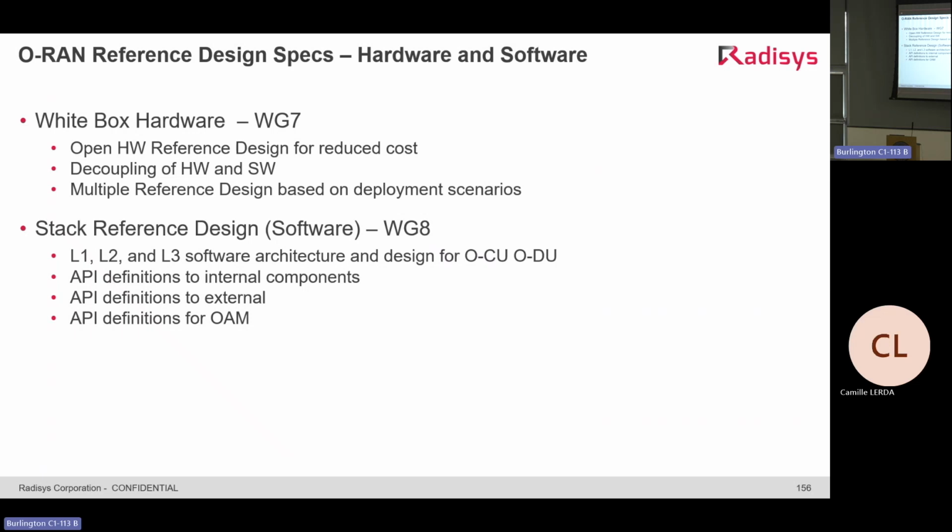So here we've been focusing on the CU and DU primarily because that forms the heart of the main processing elements of the RAN, the CU and DU. So we look at all the layer-wise implementation design and the required architecture. And of course, this is still an informative kind of specification, not a normative specification. And what we've done is gone into a higher level description of a possible reference implementation, the design aspects of it, plus a whole lot of focus on the APIs. When I say APIs, the internal modules of what constitutes a CU, DU, what are the elements of processing, some of the call flows, and gone to a certain level of detail. I'll cover some of the details in the later slide. And of course, the external interfaces and the O&M aspects also are of focus here.